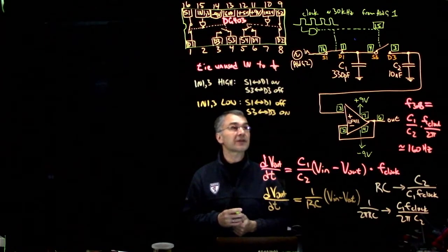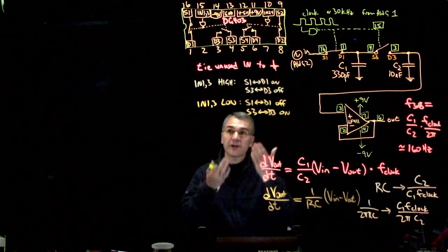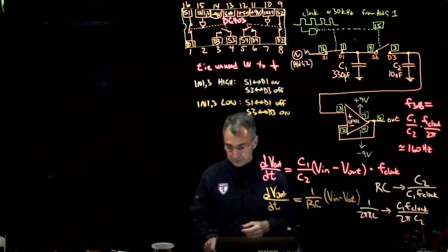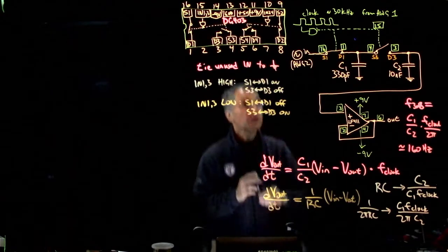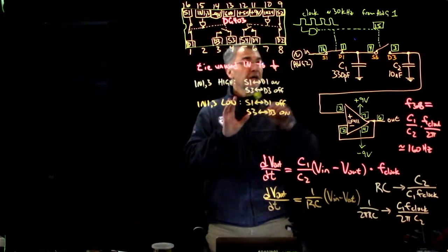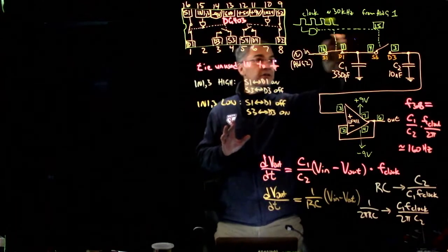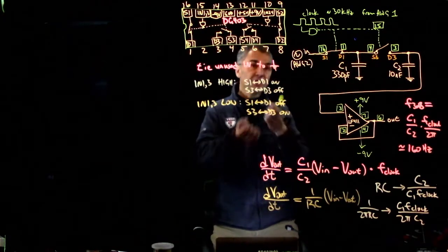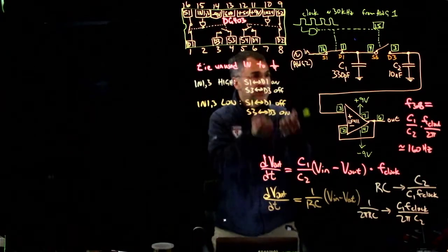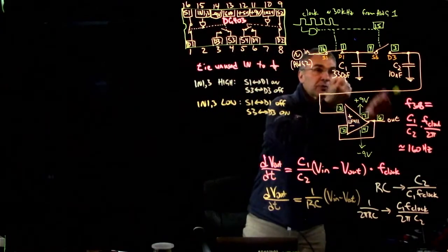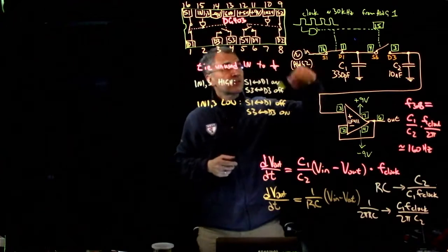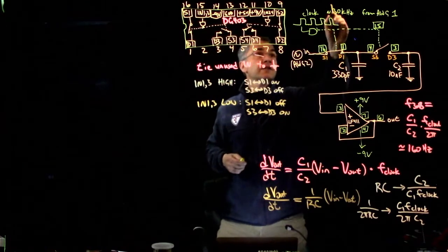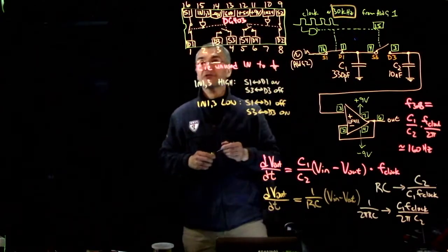So let me see if I can explain, hand-waving first, how it works. First, let's just point. We have a ticking clock, which is basically setting the time scale for this operation. Something happens. There's a shuffling back and forth of charge between two capacitors every tick of the clock. And it turns out our clock in this case will be about 30 kilohertz.